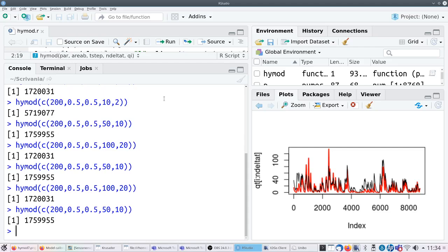And when do you make larger errors? When the river flow is higher. Because low flow is 2 orders of magnitude lower than high flow. It means that if you make an error in the low flows and you square it, it becomes negligible, negligible in terms of the metric sum of squares that we are using. Okay, so it is understandable. If you are interested in the low flows, the sum of squares is not a good metric. And this is, as I said, another important consideration.